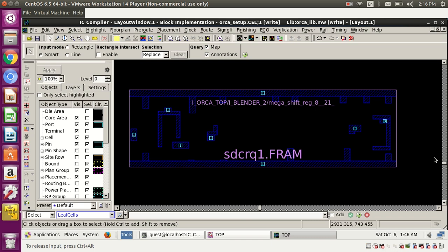I've shown you that report timing part now. Even before that, the first thing after placement or after routing is to check the first validating path. There you can check that the data path is optimized. First there will be a clock root pin, clock latency, clock network delay, and then buffers, all those things, and then the CK pin will come, then the Q pin, and from the Q pin it will come to the D pin in the data path.